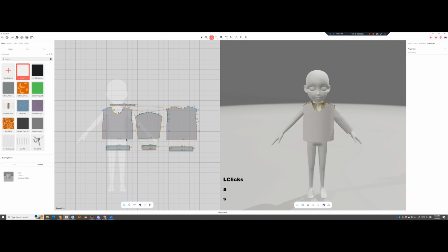Press S for the line selection tool, or you can also click the line here and then hold Shift to click multiple lines. Right-click to select Offset Inner Line and give a distance of 23. Select the internal lines that we just created and scissor.